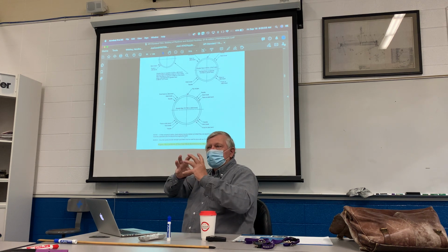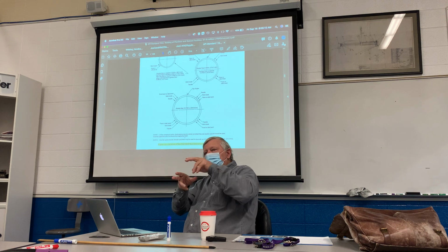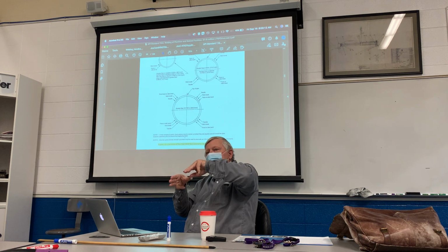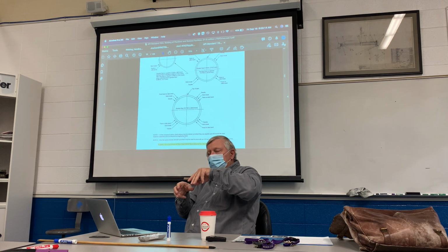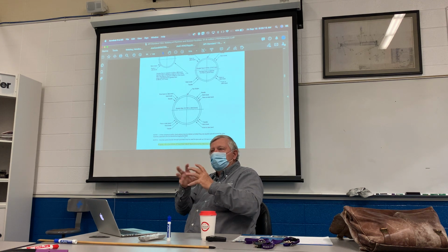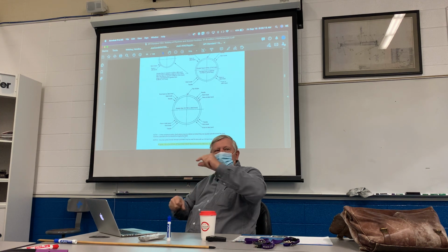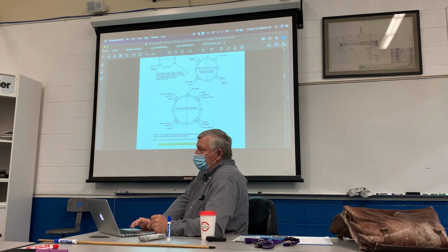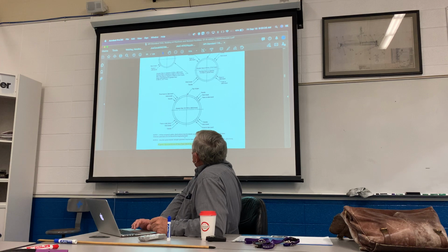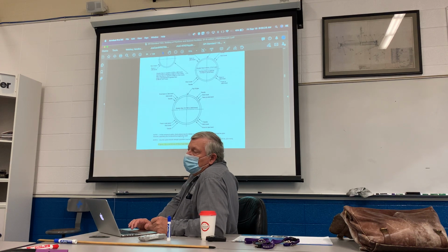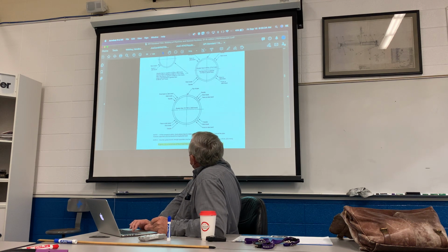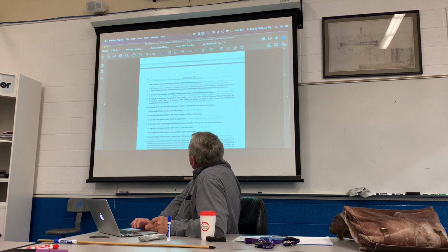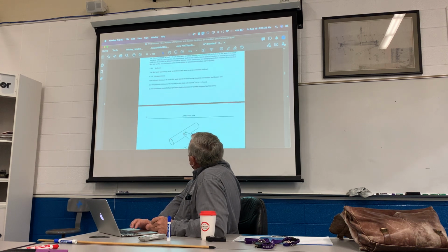Because sometimes those longitudinal seams get in the way of you making your cut, to cut your straps out. So what they're saying is you gotta position them so that you don't end up using a longitudinal weld in your testing. Nowadays they're much stronger, but when this was written, we had a lot of problems with seam welds bursting, ripping open. So now they're much stronger. Okay, questions on that at all? Did I go too fast?